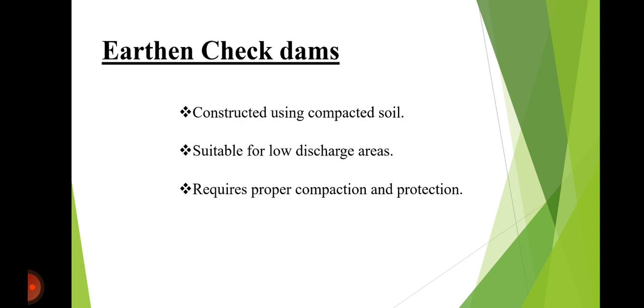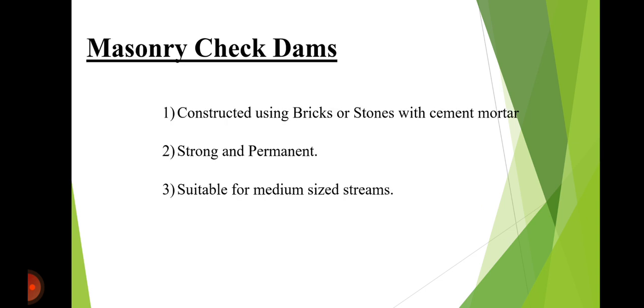Earthen check dam, constructed using soil or compact earth, suitable for areas with low runoff, requires proper compaction and protection against overflow. Constructed using compacted soil, suitable for low discharge areas.